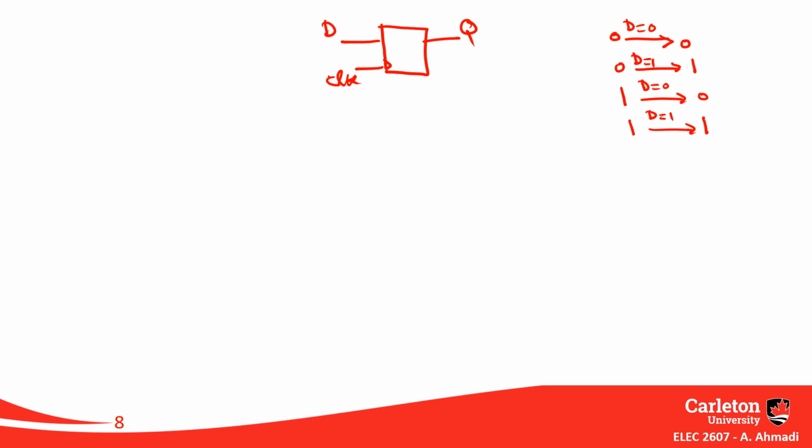It's a very basic question if I ask you this. For T flip-flop, it might be slightly different. For T flip-flop, if I have a T flip-flop and the same question. Let's say my current value saved on the T flip-flop is 0, and I want it to stay 0, no change in the value. So what input do I have to apply? Exactly, T equal to 0.